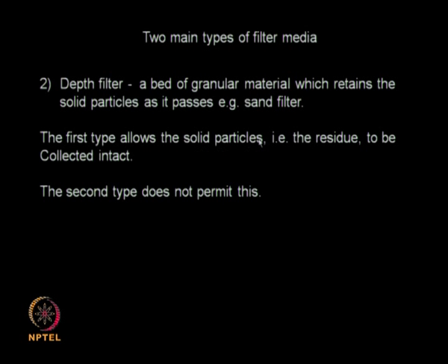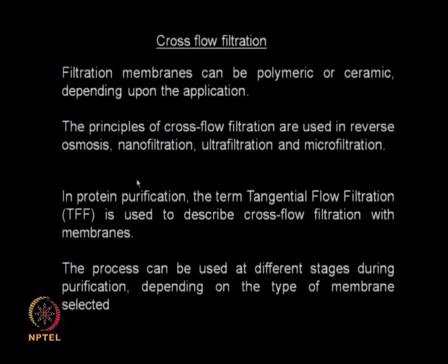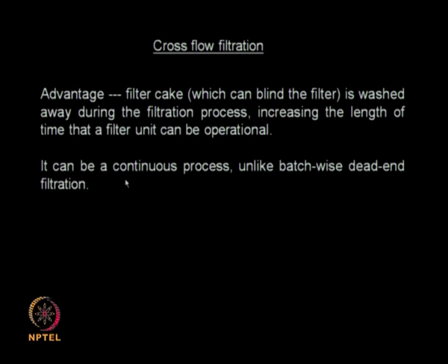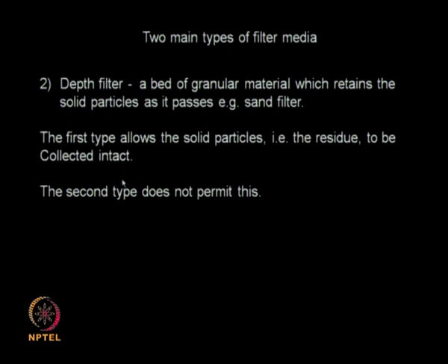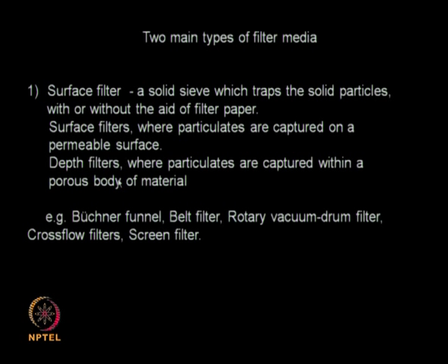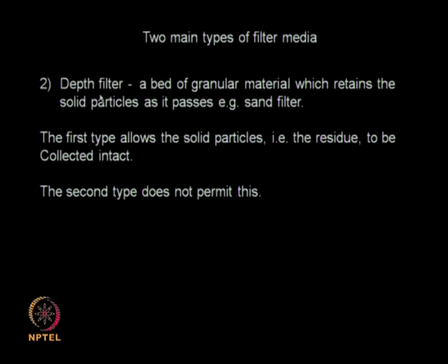The surface filter allows the solid particles, that is the residue, to be collected intact, whereas this type of depth filter does not allow you to collect the solids intact. So here we are more interested in the liquids, and the amount of solids that is present is not very large. So in that situation the depth filter is ideal.